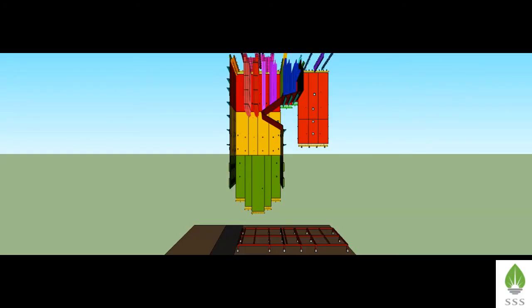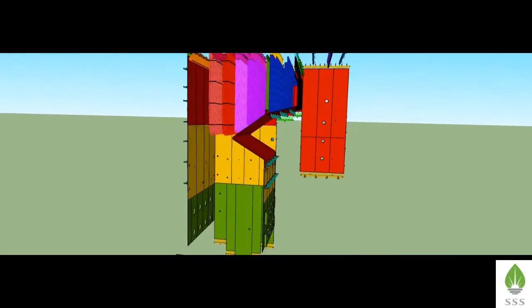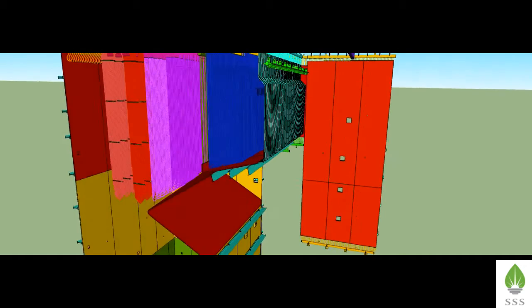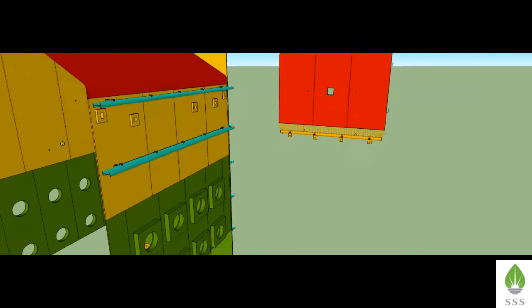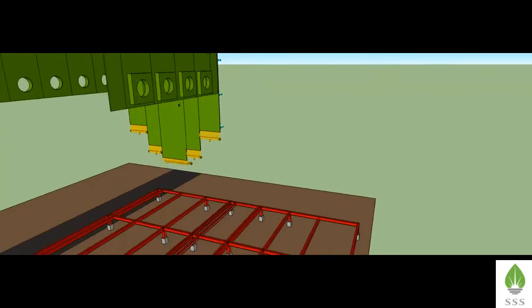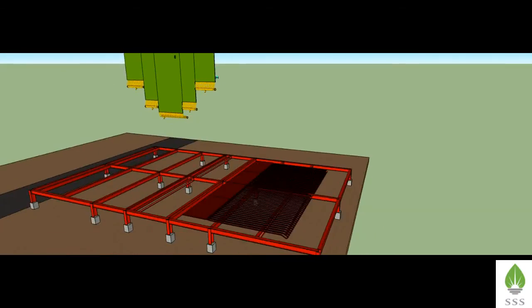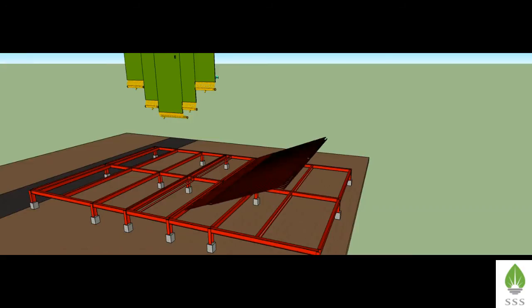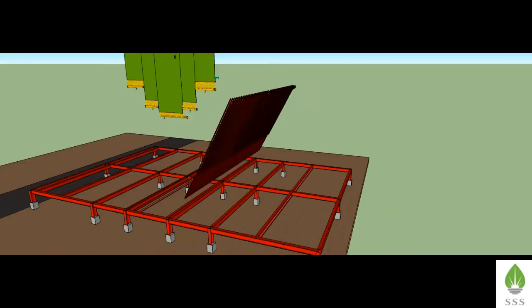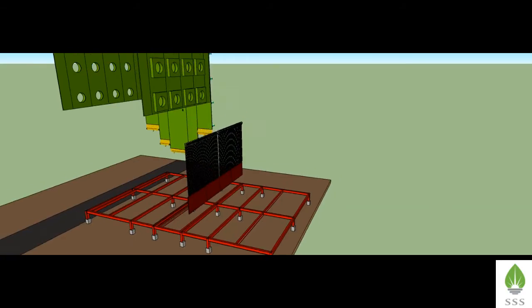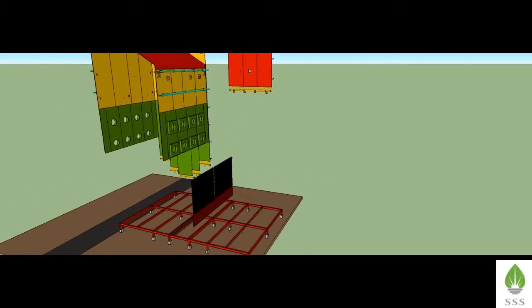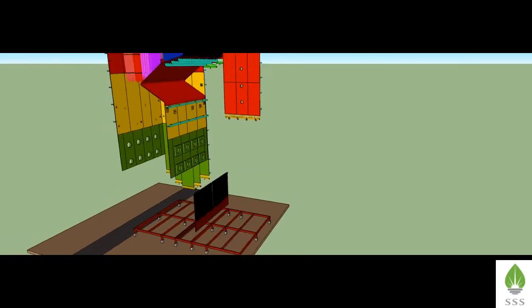Now we have to erect the balance wall panels and coils in HCP pass. Lift and erect the cage front wall top panel. Top portion cage front wall panel consists of bare tubes without fins.